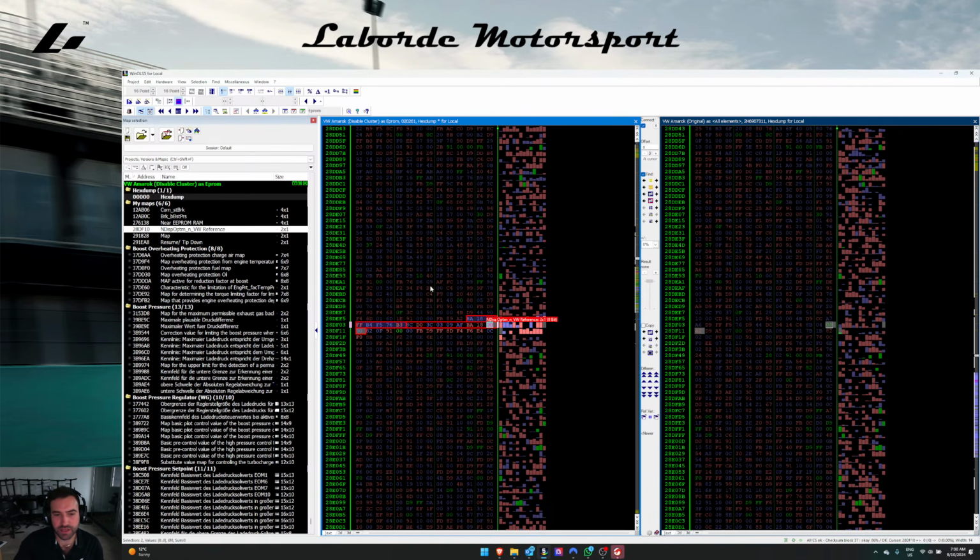So I'll just NOP the operation, meaning that in assembly language it skips over that line, or it doesn't do anything. And then I delete the storing of a value in that variable that's then sent over the L line or the CAN or whatever it may be to the cluster that tells the cluster what engine speed the car is at, right? Because I want to hook into this variable and manipulate it depending on what map we're in and based on a series of inputs, such as those from the cruise control stalk, okay?